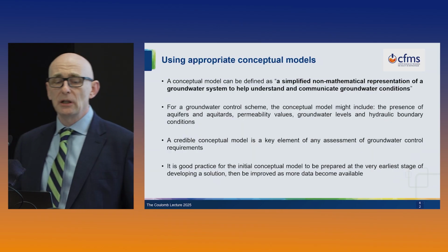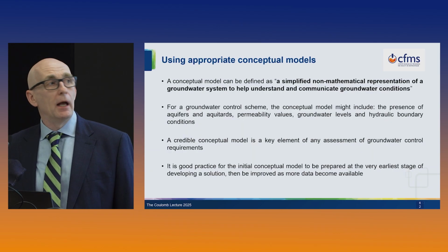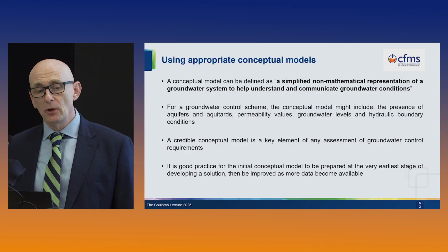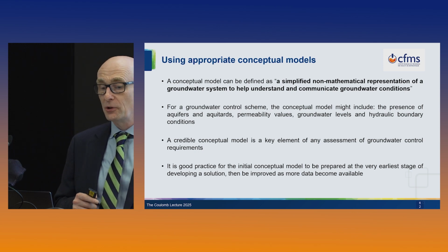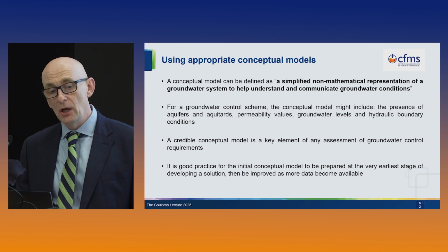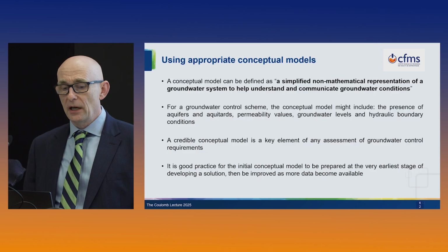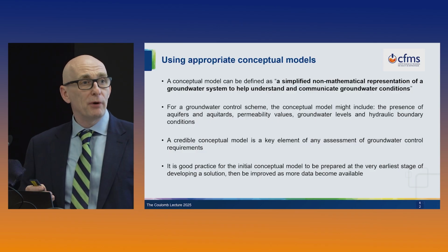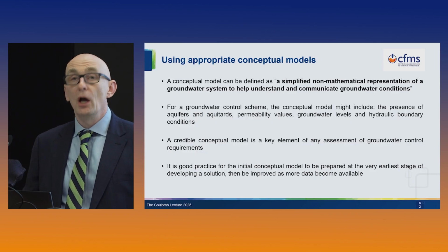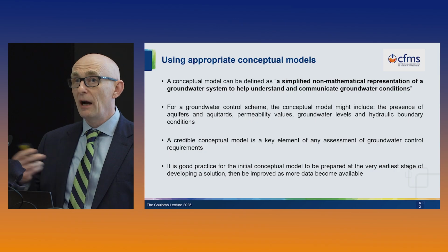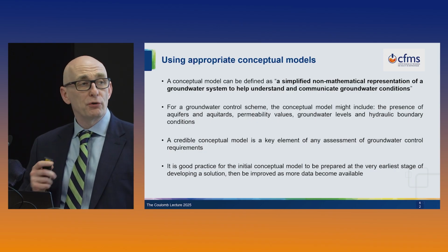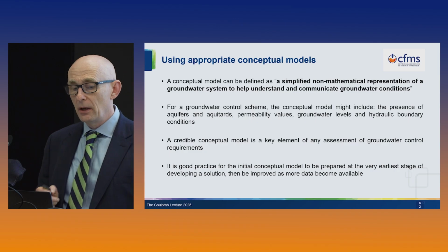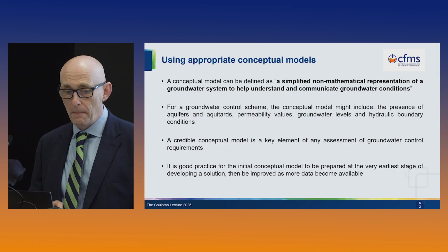I'm now going to move on and talk a little bit about conceptual models. Just to be clear on what I mean, a conceptual model is defined as a simplified, non-mathematical representation of a groundwater system to help us understand and communicate groundwater conditions. For our type of projects, a conceptual model might include the presence of aquifers and aquitards, permeability values, groundwater levels and how they might change, and hydraulic boundary conditions. And a credible conceptual model is an essential part of any assessment of groundwater control.